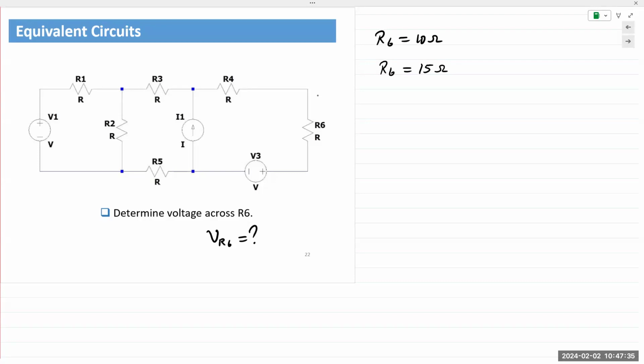Well, there was a French telegraph engineer named Leon Charles Thevenin. He postulated a theory stating that you could take a circuit and analyze it without that component present, and represent that entire circuit as a single voltage source in series with a resistance. That theorem came to be named after him, known as Thevenin's theorem, and the circuit is of course Thevenin's equivalent circuit.